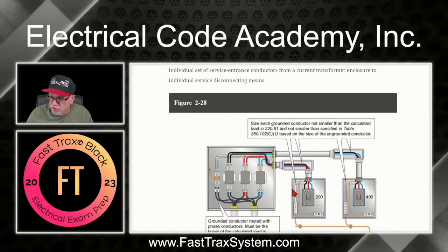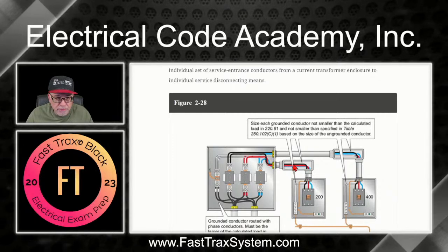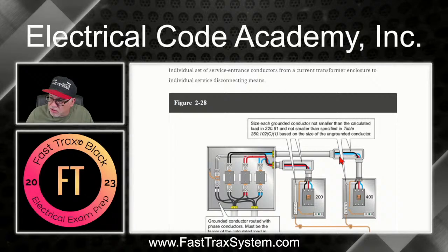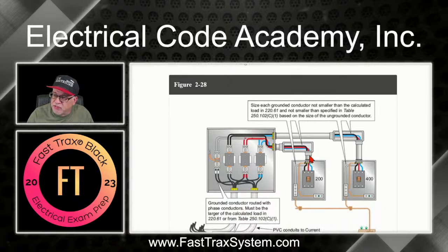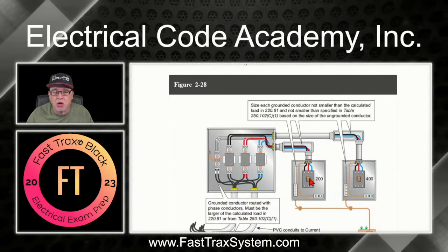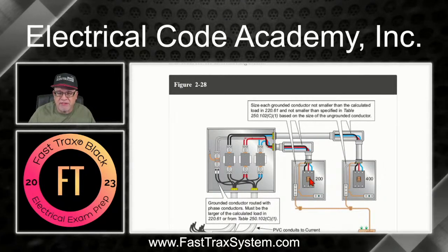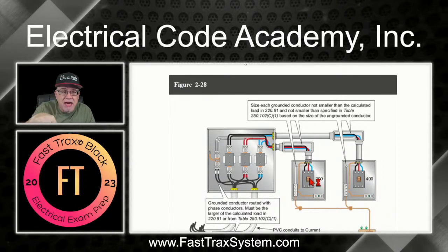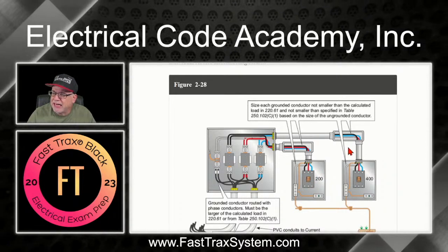And so this grounded conductor here is going to be sized based on these conductors here. And this grounded conductor here is going to be based on the size of these service conductors here, okay? Remembering that it's still going to be based on the size of our calculated load for our maximum unbalanced load in 220.61. Never forget that. Remember, what we're looking at right now is a minimum size requirement. It could be larger based on your calculation. Always remember that, okay? All right, so that's what we got here.